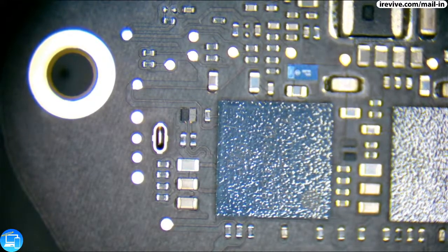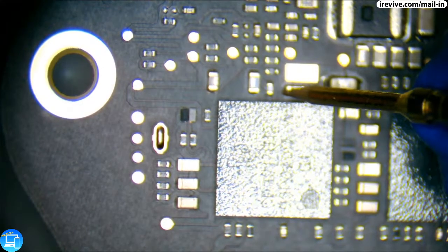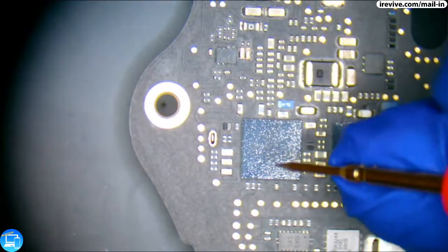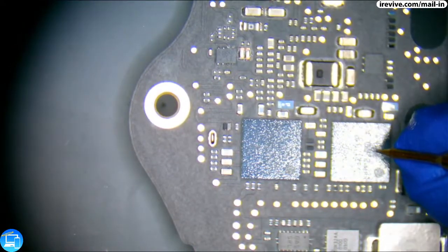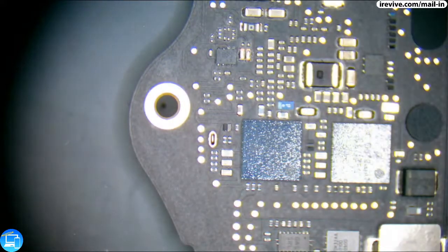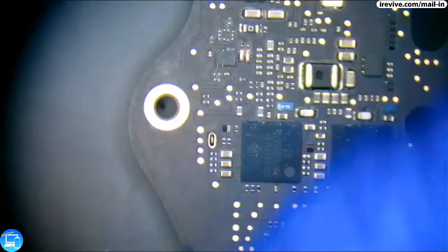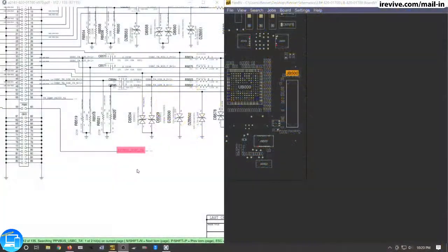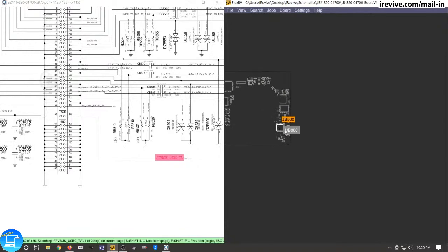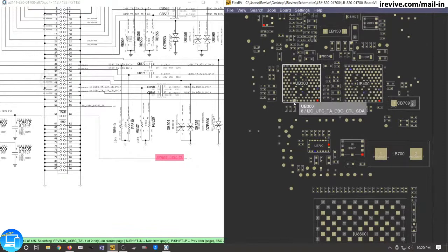Right, now that we are plugged into a different port, let's see what we get as far as that VBus line goes again. Yep, that's exactly what was going on. TA is going to stand for this specific USB-C or CD3217, and the USB-TB is going to be this specific one. So we're getting 20 volts here like normal. That's perfectly fine. Red herring. Now that we know that, let's revisit where that is specifically on our UB300. UB300 is this specific CD3217.